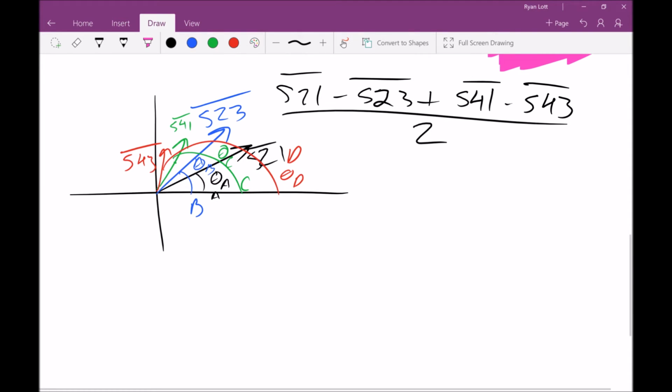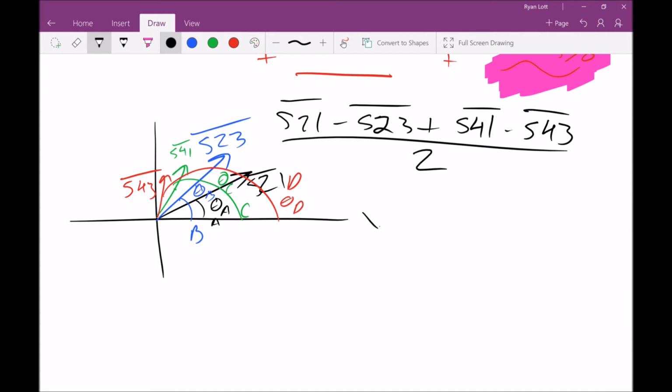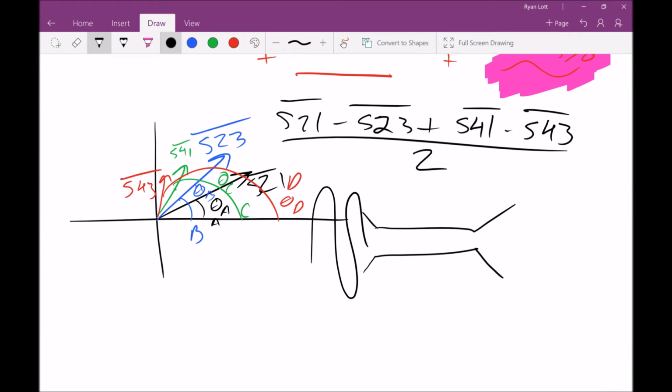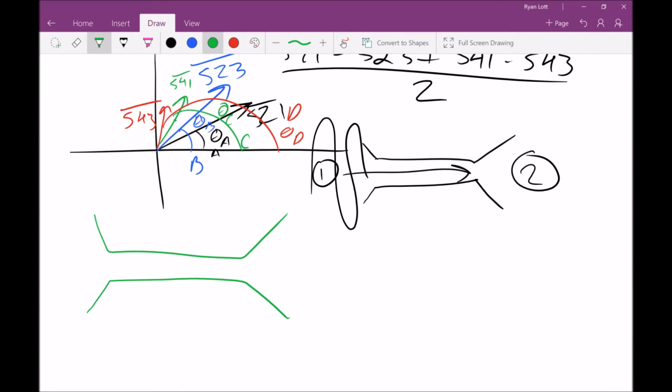Now let's do a little trick. We have this 4-port device, and we're intending to shoot a differential signal into the differential port 1, and we're intending all of it to come out on port 2. Now let's ask the question, for mode conversion analysis, what is the best way to understand exactly what creates this common component?